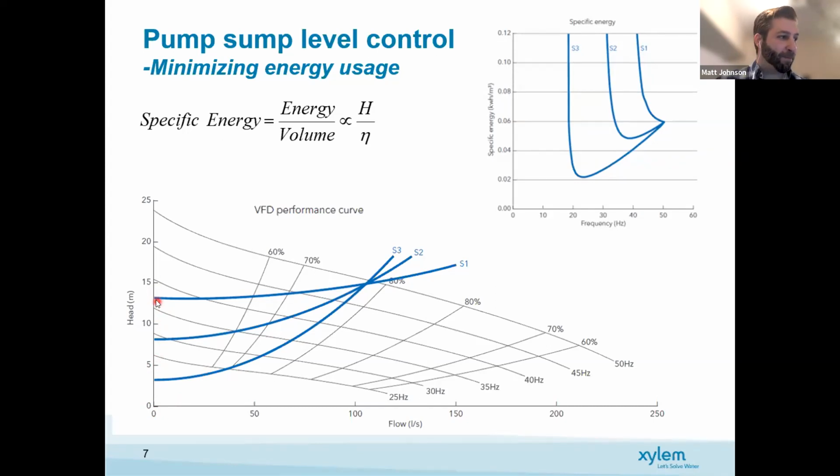In this one, it's 12 meters. But as you're pumping more and more water through it, there is not a lot of friction head. So it's increasing very gradually. But because most of this head is from lifting, slowing it down, you are not decreasing that head very much.